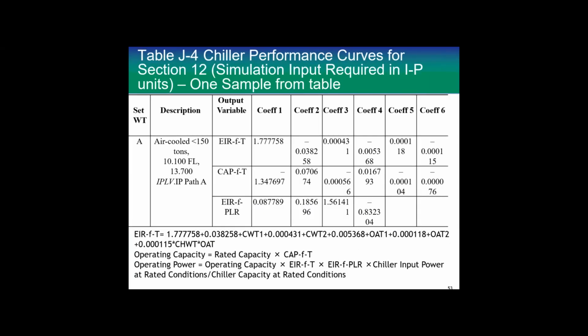So you'd come over here and this weight here would be K, and it would say 0.97 full load, which is more efficient in full load, but it would have 15.8 in part load, which is less efficient in part load. So it would be a chiller that's built to run at full speed most of the time.